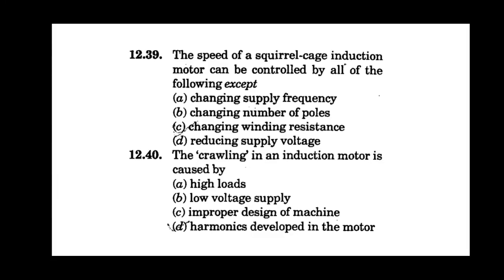The speed of a squirrel cage induction motor can be controlled by all of the following except changing winding resistance. The crawling in an induction motor is caused by harmonics developed in motor.